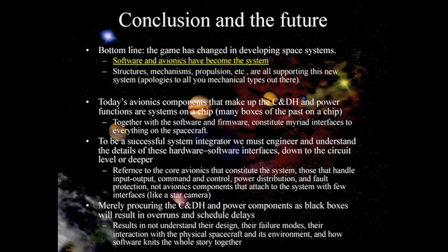I've already said this: you've got systems on a chip, you need to be careful. Well, let me bring this up. If you're going to be a successful system integrator or a PI, and you're going to take the avionics that constitute your system and say it's a commodity and I'm going to buy it from a third party, you don't own the IP that's in there, you're not going to know how it really works. They did the system integration for you. All you're doing is plugging in 22 boxes that are in one box together with the rest of your system and claiming you're doing integration. So you need to be very careful about buying somebody else's C&DH that you don't know what's actually in there.